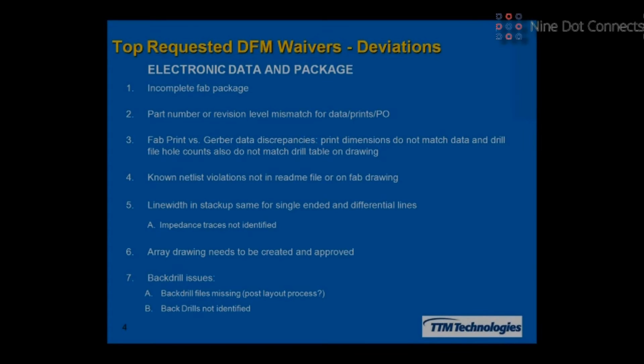I know that a lot of the OEMs here, Tier 1 OEMs here in the United States, ask for 7 mils. That's probably something that they want to live with, and they know that in the field it has some sort of long, reliable length and time. But some of these BGAs, you just can't get there from here. And I got some slides, like I said, coming up, and we can talk some more about that.